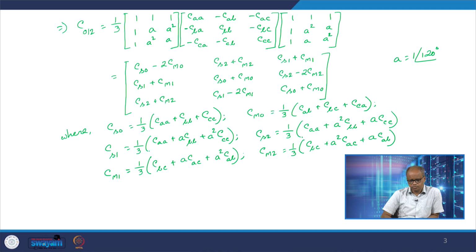So probably it will always be better to continue our calculation in the ABC domain in case my system is unbalanced, as well as my transmission lines are not completely transposed, because as we have seen, if my transmission line is not completely transposed, even in that case my zero sequence impedance matrix also would be a completely coupled matrix.